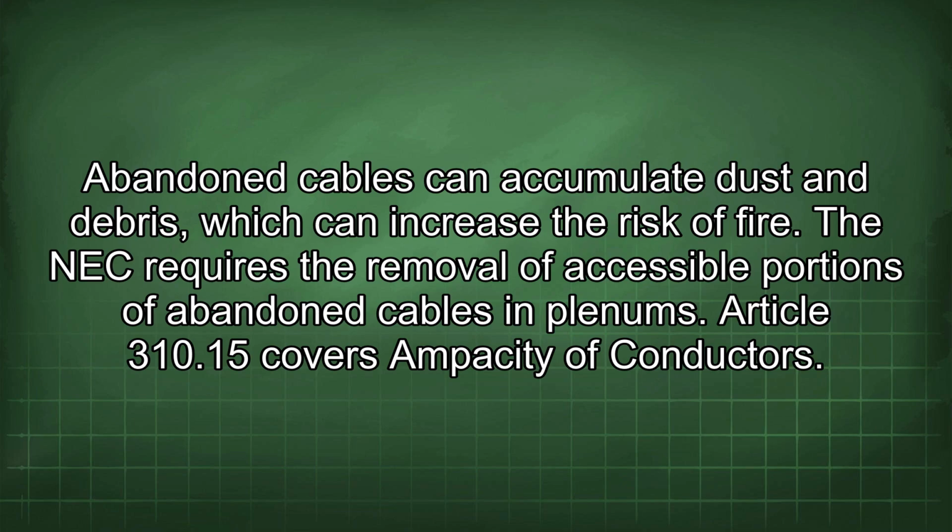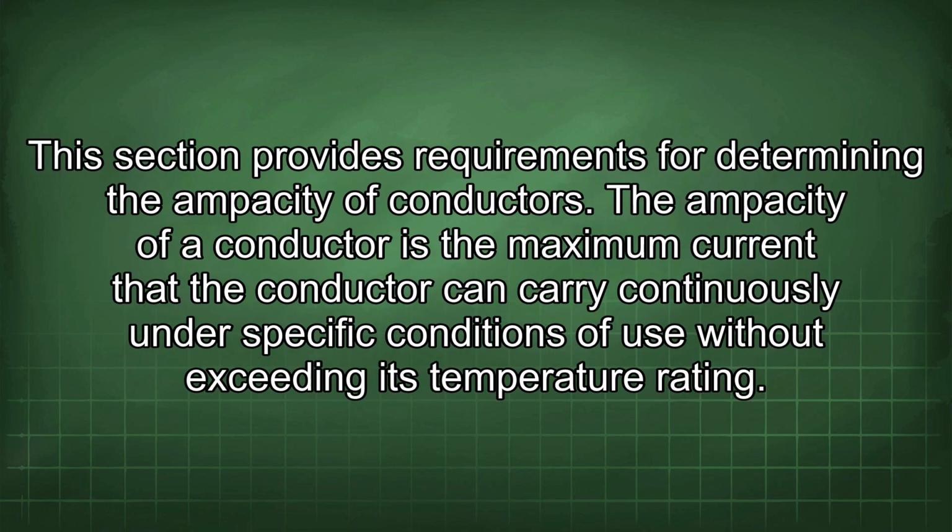Article 310.15 covers ampacity of conductors. This section provides requirements for determining the ampacity of conductors. The ampacity of a conductor is the maximum current that the conductor can carry continuously under specific conditions of use without exceeding its temperature rating.